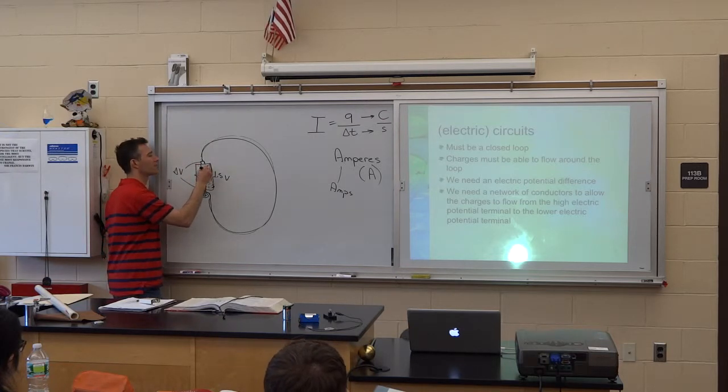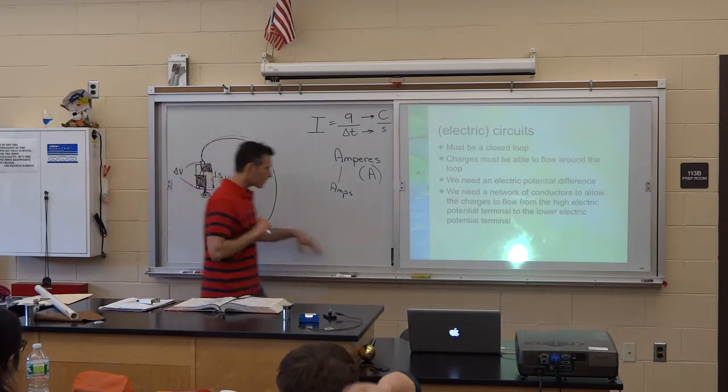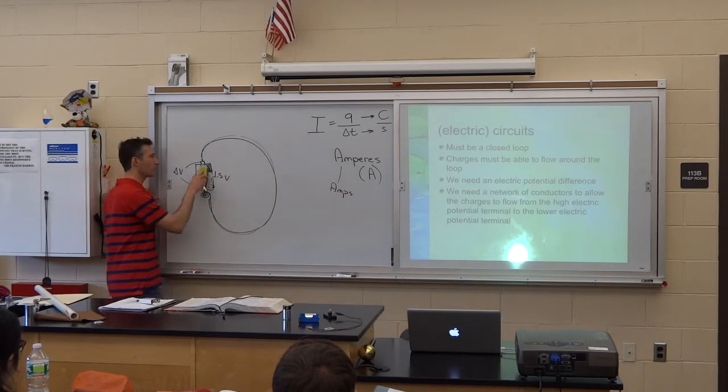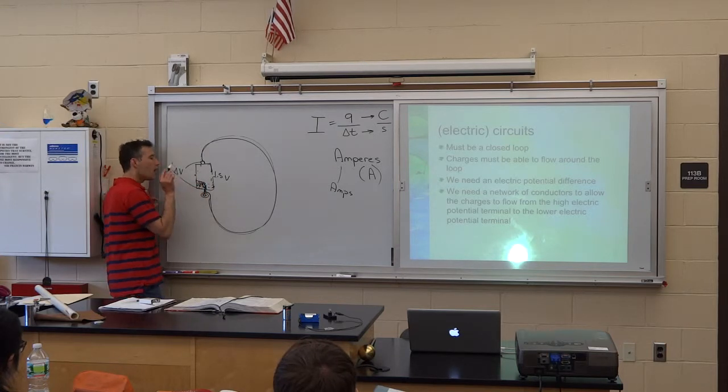So maybe a different solid will form over here. When I recharge the battery, I'm going to be reforming this solid out of solution. If I start doing that when there's still a bunch of solid there, it's not going to attach. The new solid isn't going to attach so firmly.